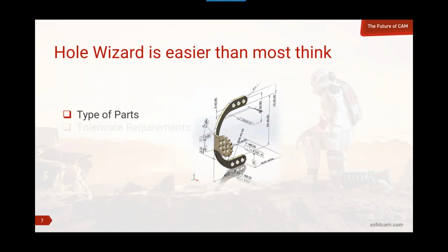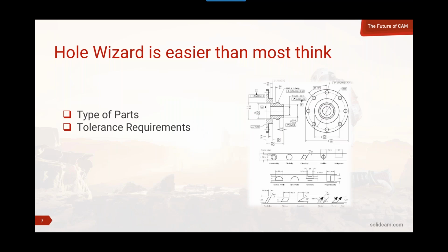Okay, now there are some things that impact that, like tolerances. Okay, we may need to do a different number of operations or a different order of operations in a process to facilitate a particular required tolerance. Let me give you an example real quick. If I'm looking at a commercial hole, I'm going to put a 1/2 inch hole through this plate, and it's not really super important, the precision with which it's put in there.